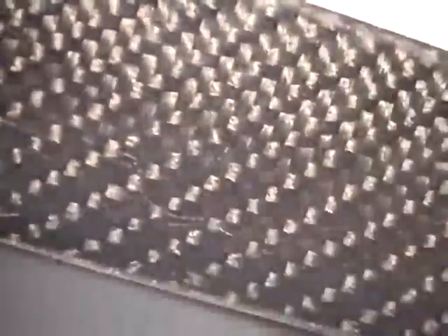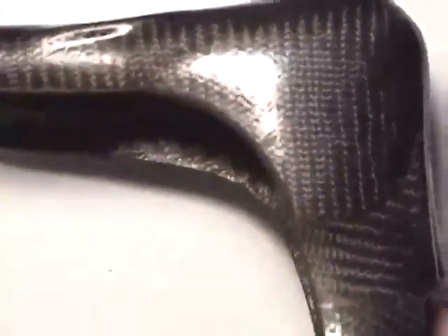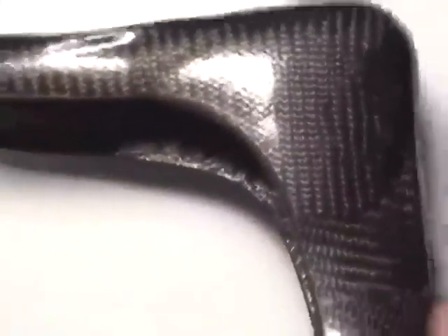So you have strength in both directions, and there are areas that have been reinforced with extra carbon fiber. There's an extra piece of carbon fiber here, a little bit more carbon fiber here, and less fiber up here. So we've got spot reinforcement, and we've controlled the strength of the layup by adding and reducing the number of layers while we were laying it up. This is a good example of how you can vary the strength and the orientation of your fibers. Now this was a pre-preg type of material, where it came pre-impregnated, we heated it up, and then it went through a consolidation process in the oven. So that's a carbon fiber AFO using pre-preg material.